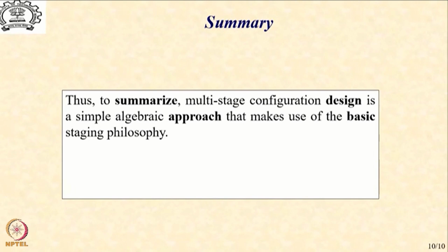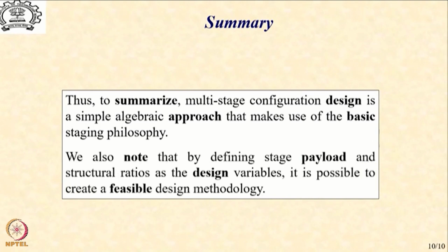The staging philosophy that we have discussed is typically called the serial or the series staging, and in some contexts it is also called restricted staging. We also note that by defining stage payload and structural ratios, it is possible to create a feasible design methodology. We will look at the solution for these in the next lecture.